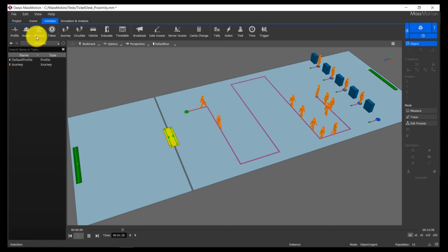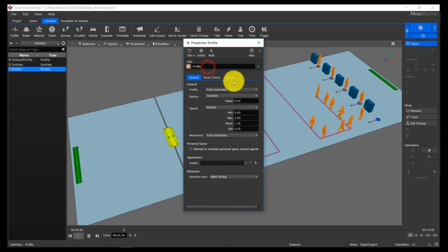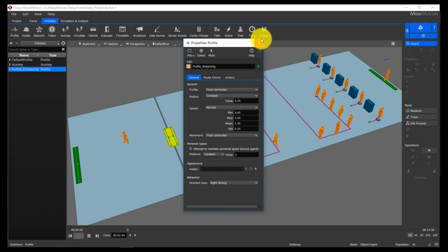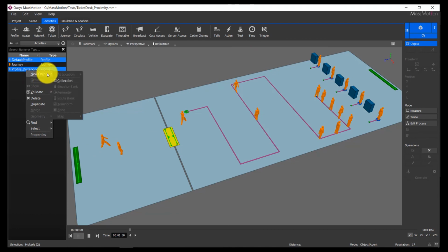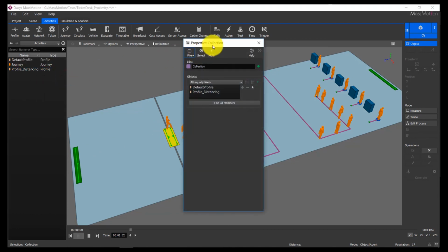Choosing to not enable this parameter ensures that flow rates meet MassMotion's calibration and validation tests as with previous versions of MassMotion. Due to a lack of data at the time of release, enabling this feature will result in different flow rates and densities achieved for standard through and calibration tests. This feature is intended to be used to compare various population scenarios within a space or varying levels of adherence to a range of physical distancing values.